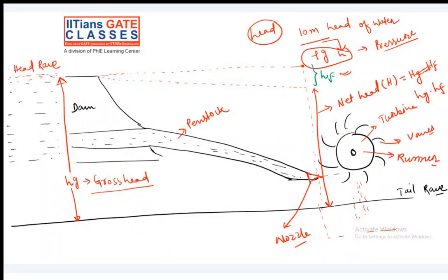So here your water is containing some power, means whatever head we have, corresponding to this we have some power producing capacity, right? And then your runner will generate some power. So the ratio of these two means what is the maximum power we do have, and out of which how much we have got converted. Got the idea that initially we must be having some power at this point, and then this power gets converted into whatever power your turbine was able to generate. So the ratio of these two is called what? Hydraulic efficiency. Got the idea?